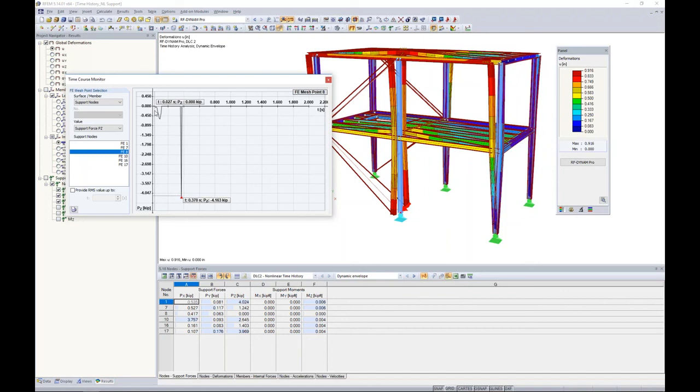We have uplift, but then at about time 0.027, it looks like we have some type of downward force, so that support is reactivated. Then it fails again. And then at about time 0.354, well, it's activated again for a short period of time. And then for the duration of the 2 seconds, it's completely failed, most likely because we have uplift forces here.